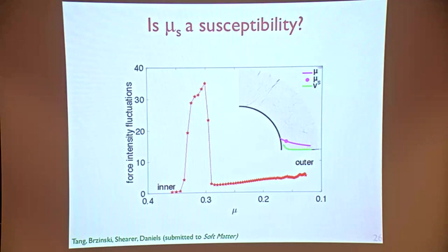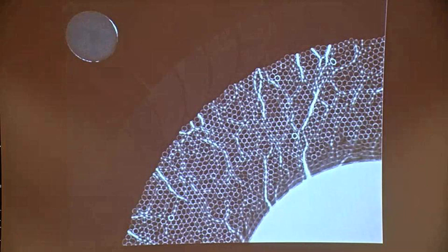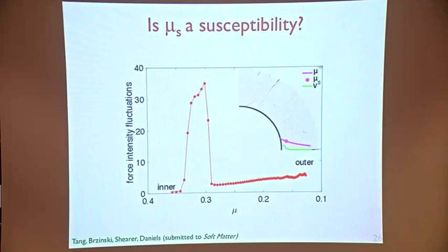I didn't tell you something important about this experiment. When we have the photoelastic particles, we have to put a lid on the experiment because we need to have a polarizer there. So I've changed my boundary drag by sticking the photoelastic lid on it, and so I've raised the shear stress slightly. Instead of being at 0.26, this jump is at 0.29. And I can't tell you quantitatively that's correct, because once the polarizer's on, I can't do particle tracking. So I have an either-or option.